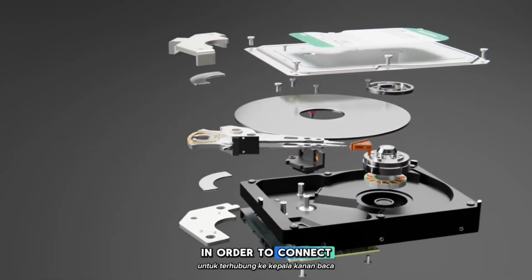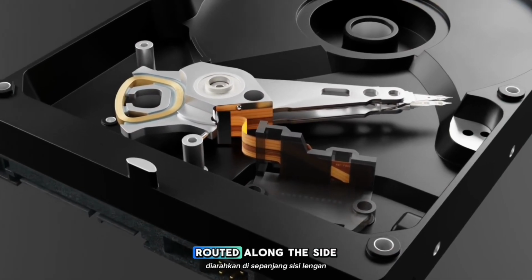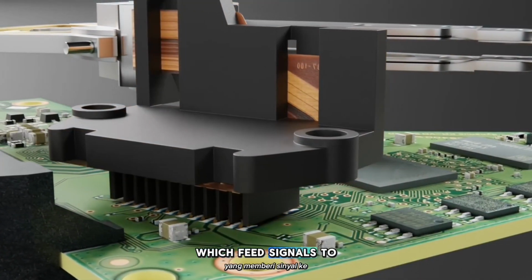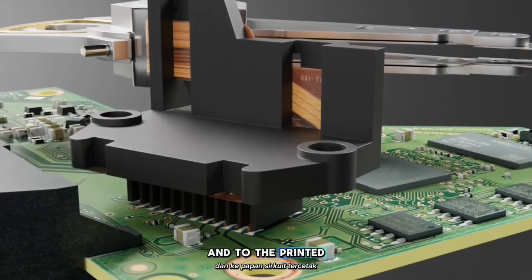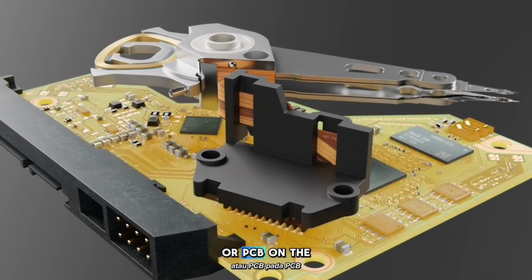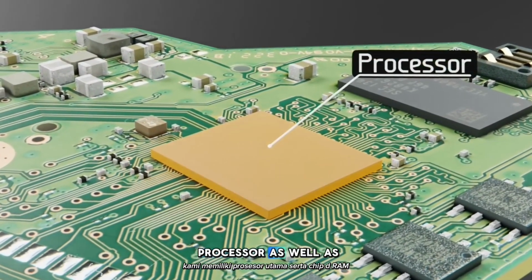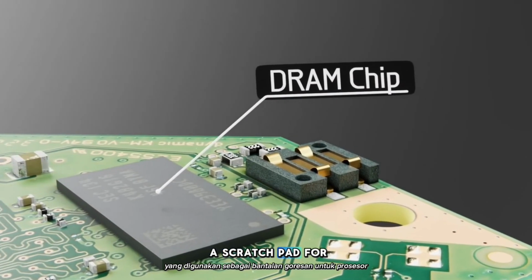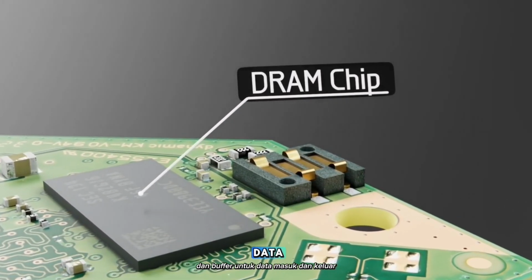In order to connect to the read-write head, a flexible ribbon of wire is routed along the side of the arm and down to this connector, which feeds signal to the outside of the hard drive enclosure and to the printed circuit board, or PCB. On the PCB, we have the main processor as well as a DRAM chip, which is used as a scratch bus for the processor and a buffer for the incoming and outgoing data.